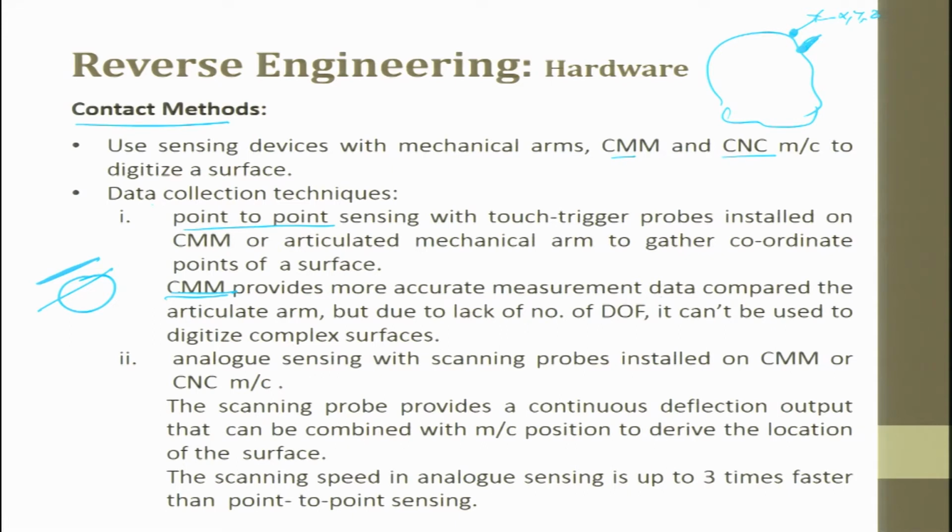If you have to measure biological samples, for example a leaf, a heart, a skin or something like that, then a CMM will find it difficult because it does not have the freedom of negotiating itself in measuring certain intricate data. One can be undercut data, the other can be internal data. For example, undercut data is something like this. This is an undercut data which is very difficult for a CMM to access, or you can also have inner groove data.